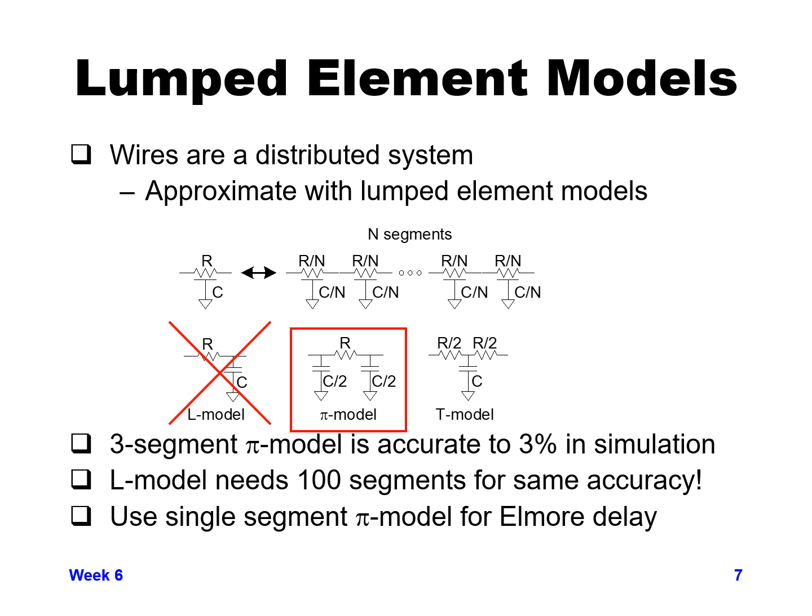So typically we wind up using a single pi model for our Elmore delay and get reasonable enough accuracy doing that. So you'll see that most often, and that's what I've always used when I've done RC pi models, RC delay for my simulations at Intel as well.